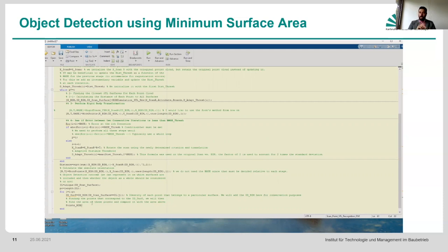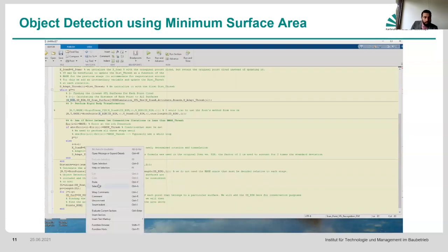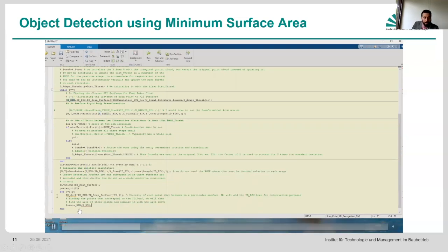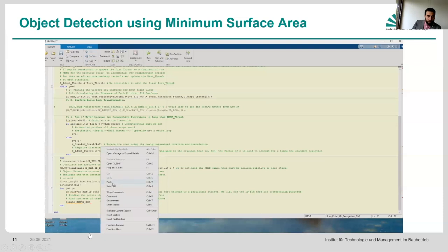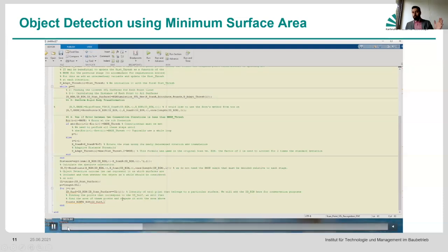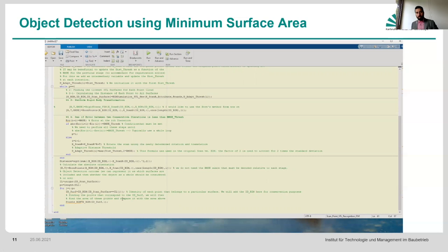Because if we want to do the actual ones, we now have to project it onto the surface again, and we have to find the boundaries. We don't need to do that. We already have our X_BIM, right? So we go to points_BIM, and that is equal to X_BIM of ID_surf, and column. That means the rest of the columns of the X_BIM. So these are the points for a particular surface, for the first surface that has correspondence between the point clouds and the BIM, okay?